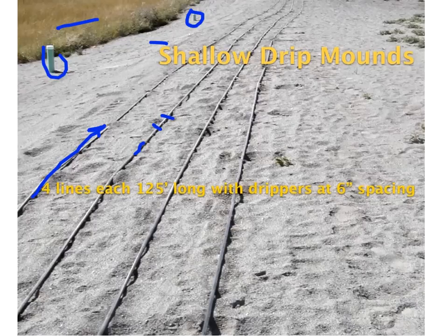No, they certainly are not exactly on contour, but they're more than close enough. I mean, the drip line is full of holes, correct? And when you switch off, you get a little bit more water out of there because a little bit drains out. But the height difference here isn't going to set up a vacuum that's going to suck dirt back into the system.